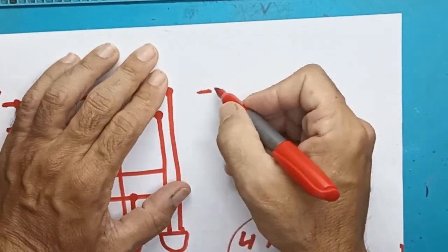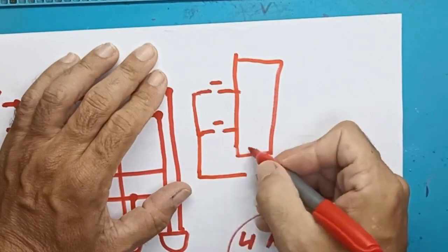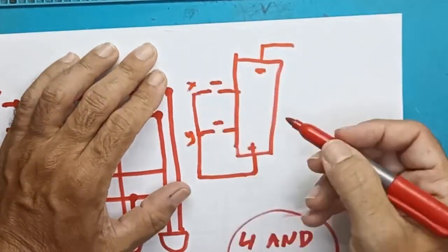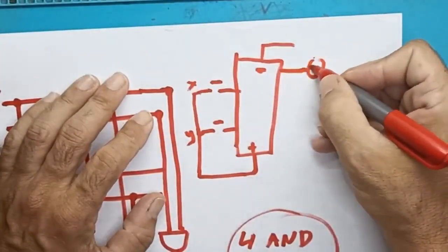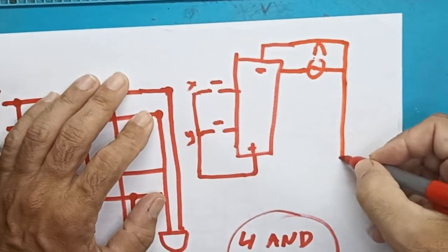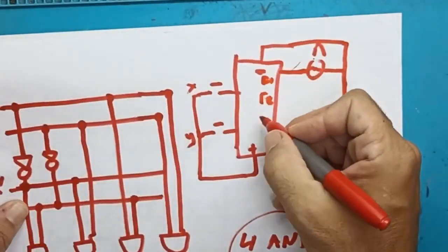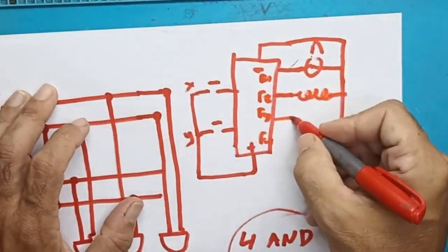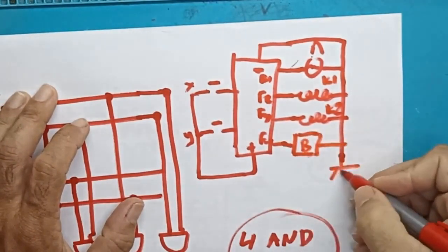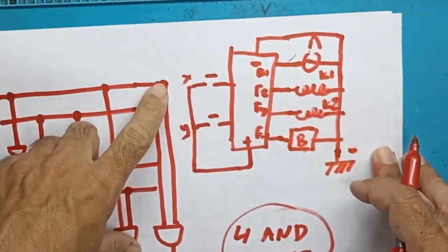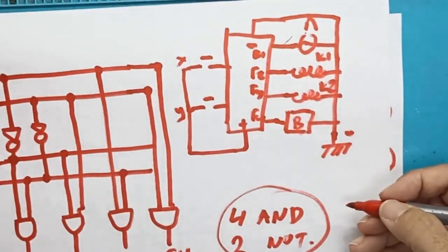What will we have outside this box? We will have the switches, the two small buttons start and brake, and at the output will come out: at the first output we will have an LED, at the second output a relay that will give us the first rotation of the motor, at the third output a second relay. I designed the relays like this over here. And at the final output, we will have a buzzer that will give us the alarm when we press the two buttons together. So now we are ready to build our circuit, theoretically at least.